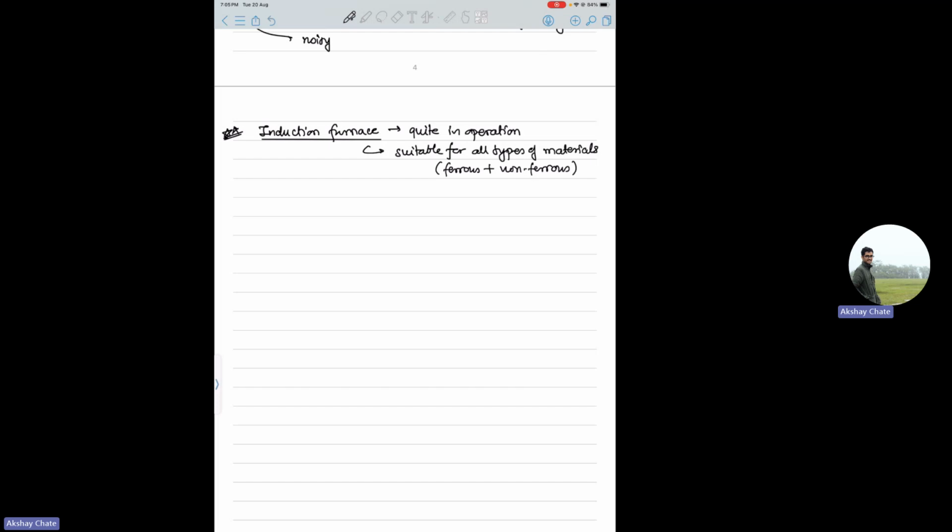Yeah, there are steels and then there are cast irons. So in cast irons, there are different categories such as grey cast iron, white cast iron, malleable cast iron, ductile or spherical graphite or nodular cast iron. Grey cast iron basically has flakes of graphite. Some points I'll give you, because the composition etc. you can read on your own, since it's all theory. You cannot remember those things, and in many competitive exams they are not asked. So don't worry. But some things are there that you should remember.